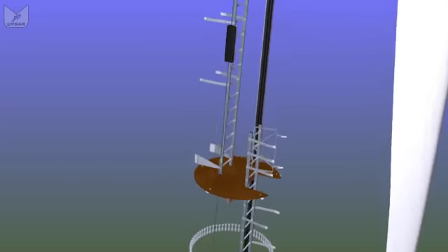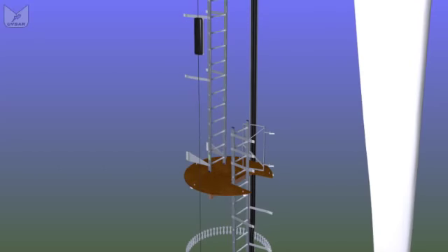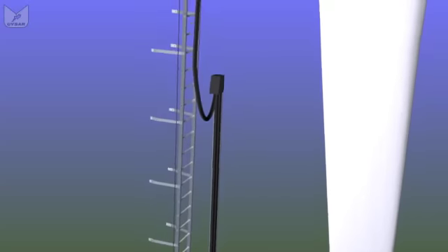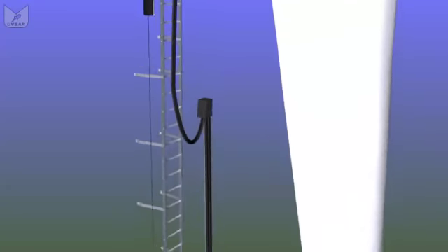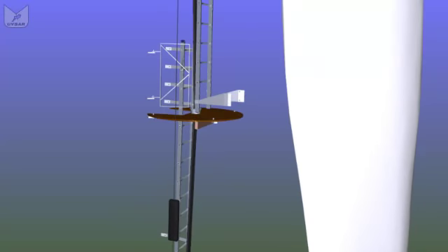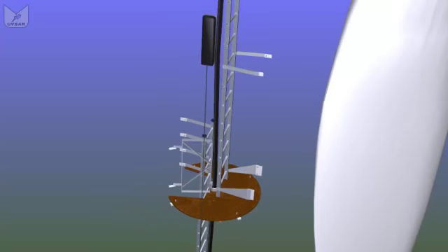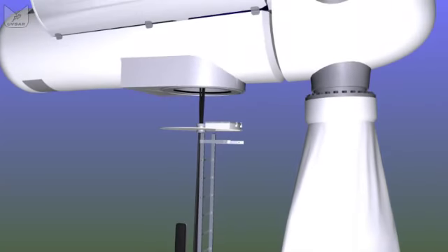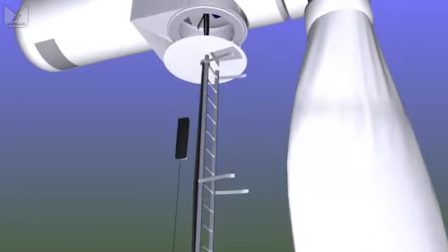But eventually, the main cables stop being attached to the wall, and they hang freely in the center of the tower, so they can twist as the nacelle rotates to face the wind. If they twist too many times, the nacelle will spin itself around to remove the twists. But as we move up, now the cable goes through a hole in the center of each platform, and at the top of the tower we have a steel platform with a sealed trapdoor, which we call the yaw platform.